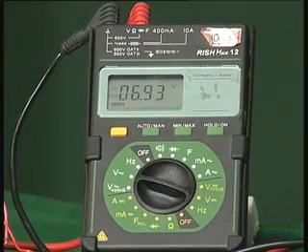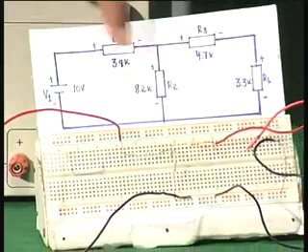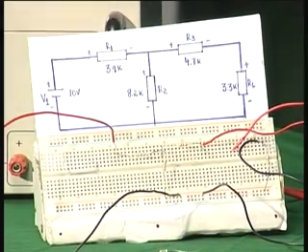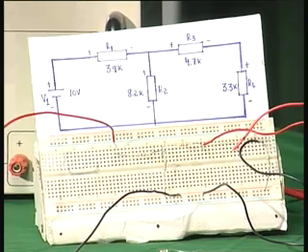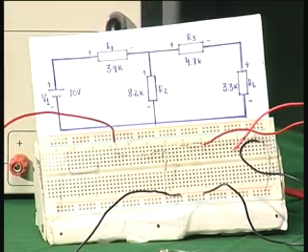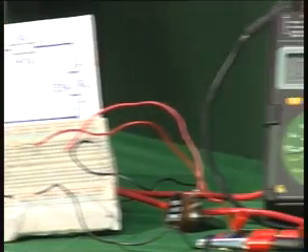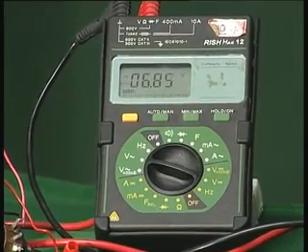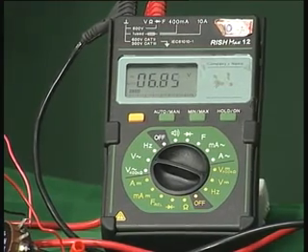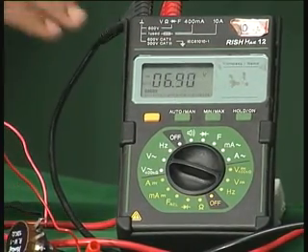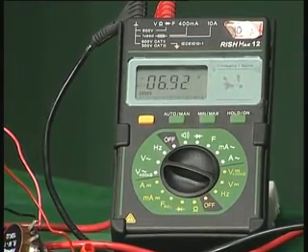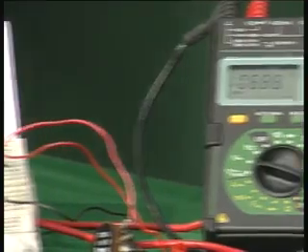The difference is because these resistors are not the exact values as mentioned here. They have some 5% or 10% tolerance, and therefore the actual resistance value will be slightly different from the values that I have specified here, and therefore you get the actual voltage corresponding to this combination. But you can see it is very close to what we actually discussed. This is the Thevenin's voltage, because I have removed the load and am measuring the output voltage using the multimeter. So, this is the Thevenin's voltage V Thevenin that we have measured.